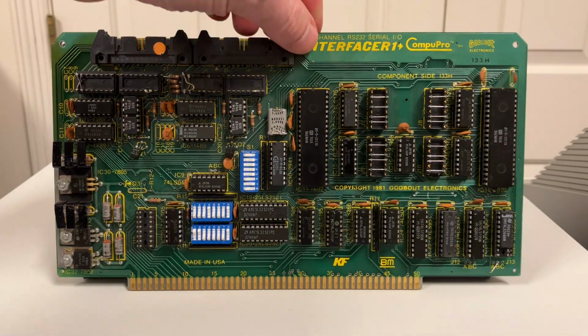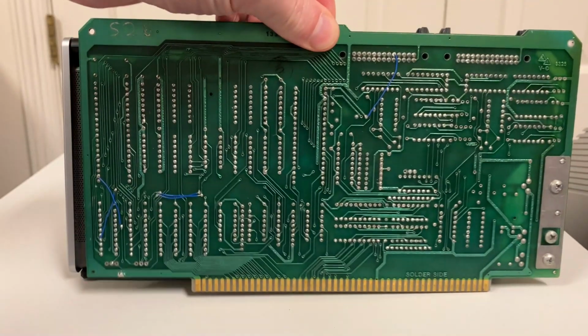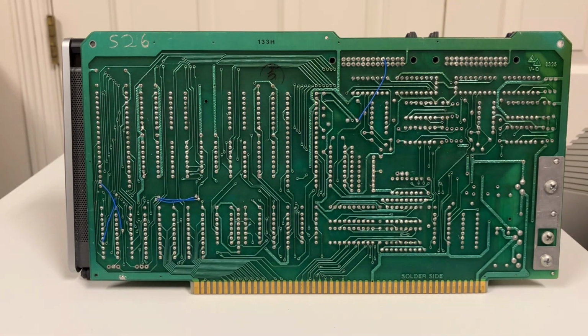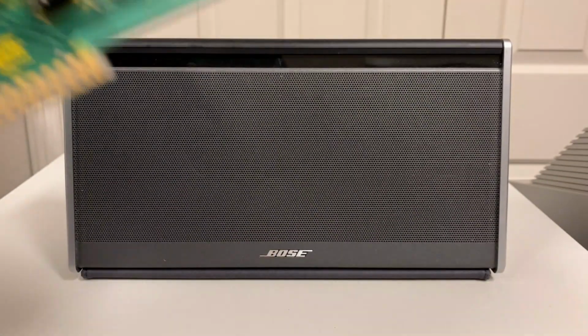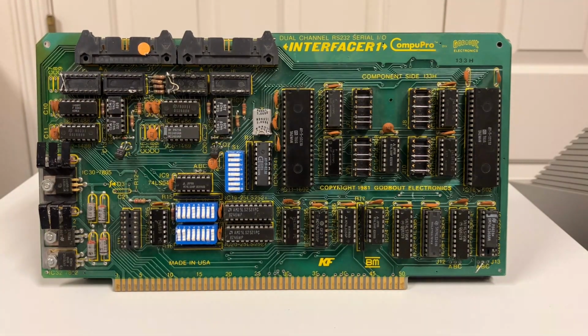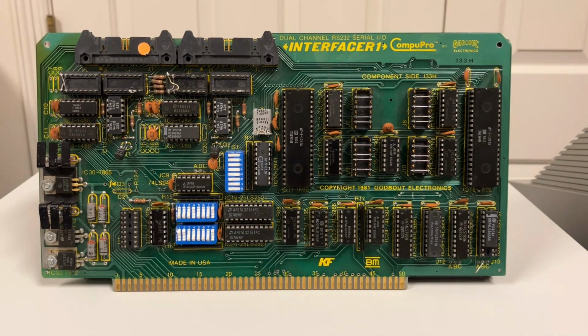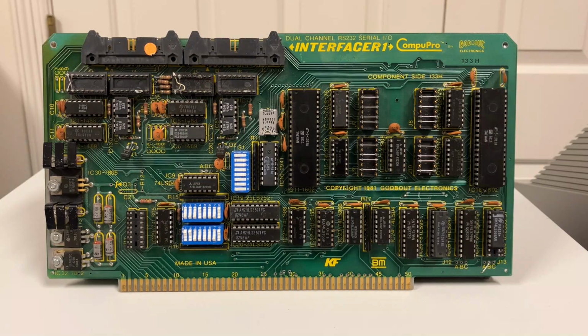I got those cut, and then on the back of the board, I have 2 blue wires that basically just swap those 2 signals because the interfacer had transmit on bit 0, receive on bit 1, and I needed them the other way around. All right, and then of course it's positive true logic instead of negative. And so I don't have to worry about changing out buffers. I just leave the buffer that's in there because it's already a non-inverting buffer. And at that point, our serial port for the console is good to go as well. So we'll set this up and take a look at it. And we'll not have to use a 2SIO board because this board will serve as our console port and as our cassette port.